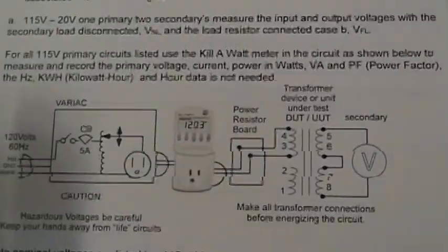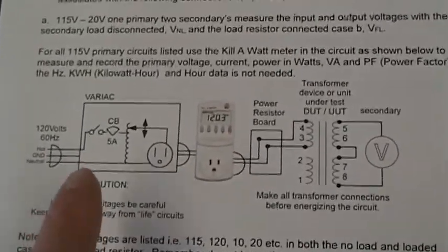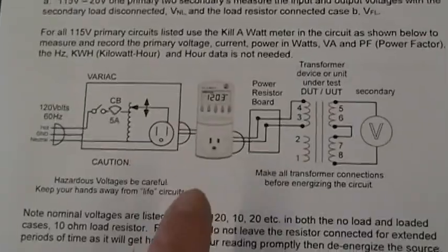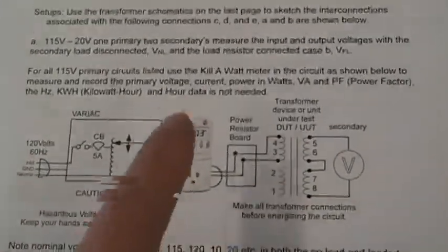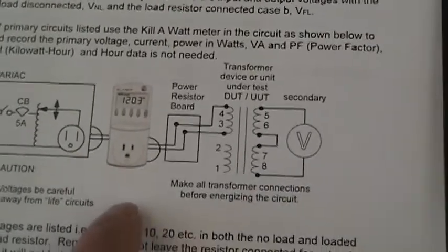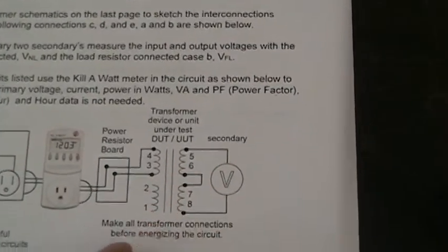In part 3 of the laboratory, we're going to do the polarity tests and voltage regulation tests for the transformer. Since these are fixed voltage tests, we're not going to change any voltage for the transformer. We can switch over to using the kilowatt meter, which we used last week with the single phase power lab. And then we're going to just measure voltages and reconfigure.